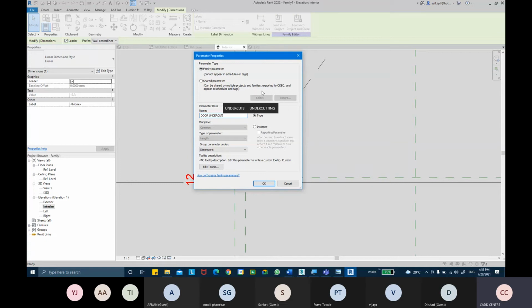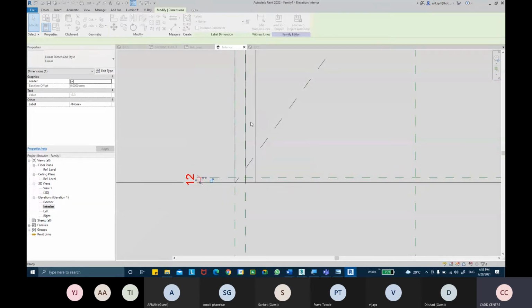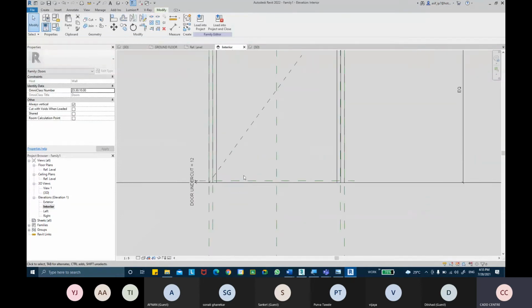Generally, you see the door is not touching the flooring. There's a little space. It's above the floor, so that your door doesn't scrape on your finished floor. Otherwise, it might not budge, it might not open. So an undercut is required below the door as well. So that's my door undercut.